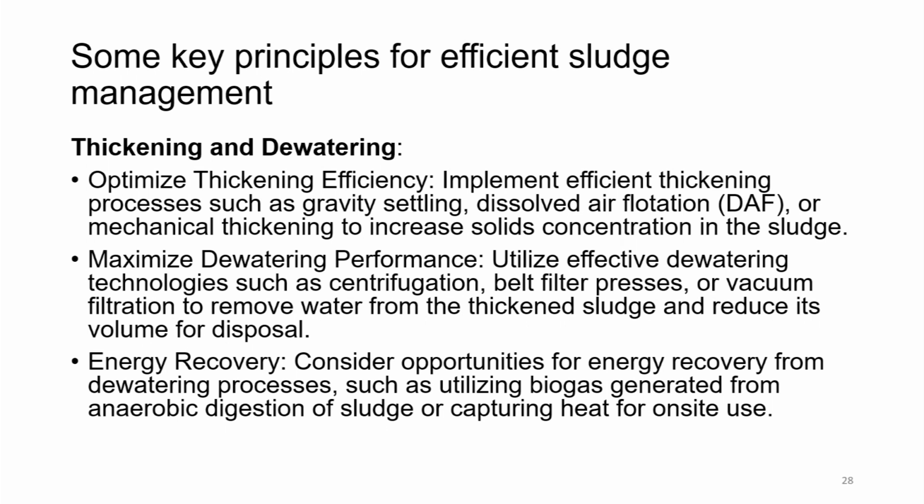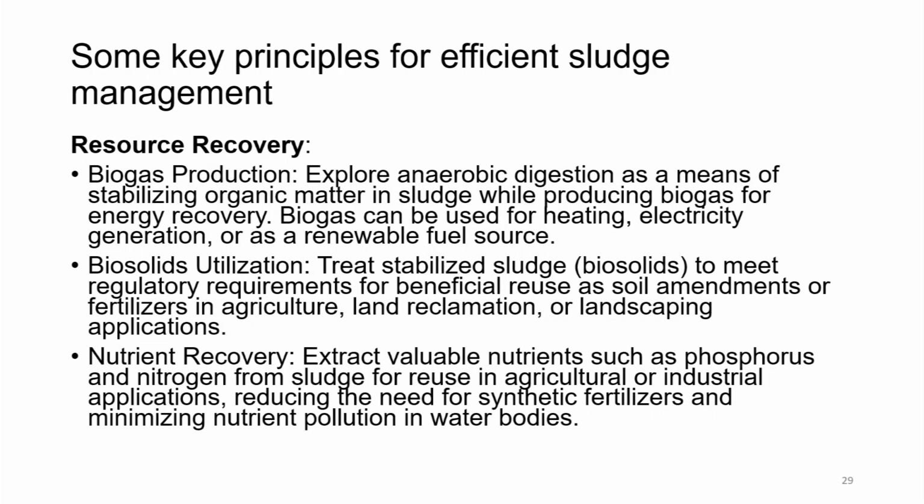Energy recovery. Consider opportunities for energy recovery from the dewatering processes such as utilizing biogas generated from the anaerobic digestion of sludge or capturing heat for on-site use. Resource recovery.